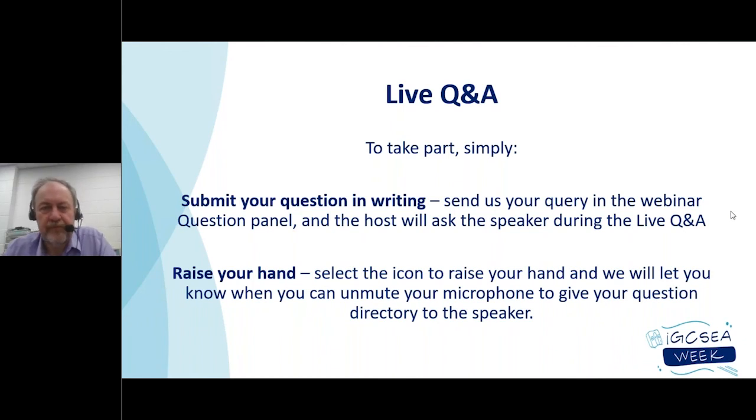Next question, please. What impact, if any, does humidity have on surface energy? Let me make an initial comment, and Dan can make a comment. Look, clearly, once you introduce humidity, the humidity will compete for sites on the surface. So it does get a bit more complex in terms of what's happening with humidity. Generally, I would expect surface energy would go down as we start to passivate the surface with water molecules. Dan, would you like to comment on that question? Because you might have a bit more experience with doing that.